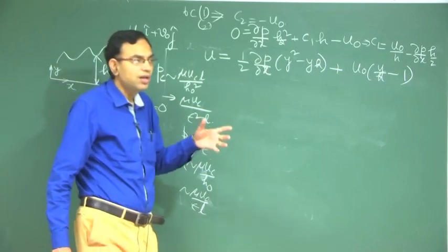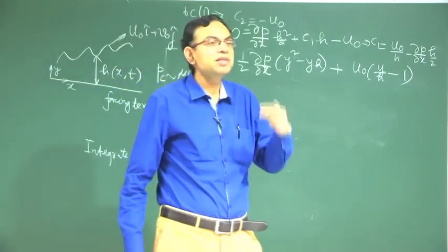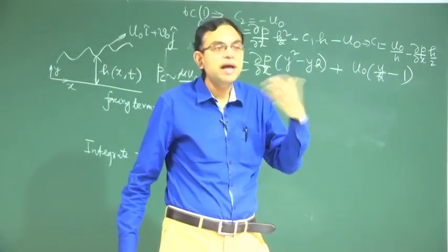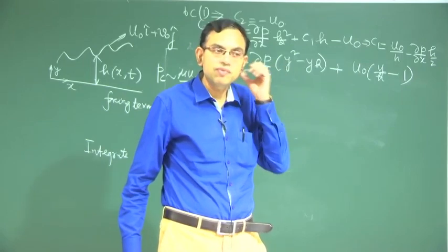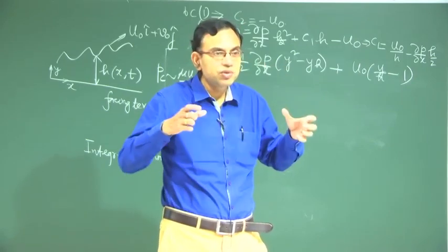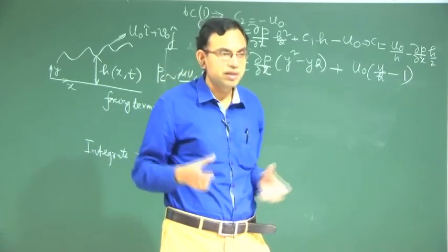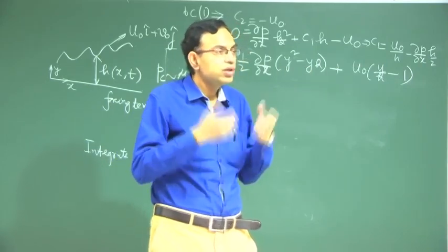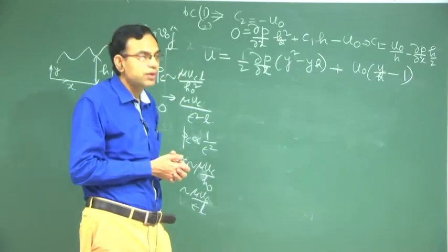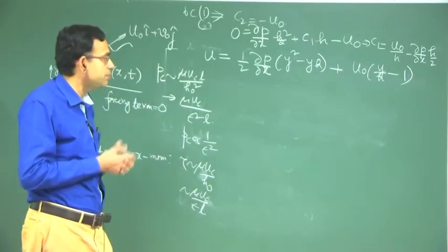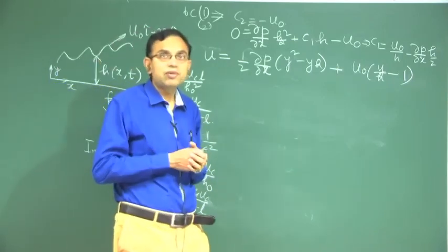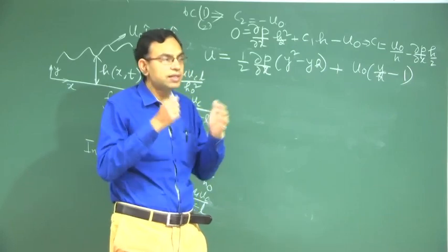Epsilon being small, the pressure is much more significant in lubrication theory than the hydrodynamic shear itself, and that is why the pressure distribution dictates the force on the boundaries, and that is why we need to develop a governing equation for the pressure distribution. So, the strategy that we will follow is very simple.